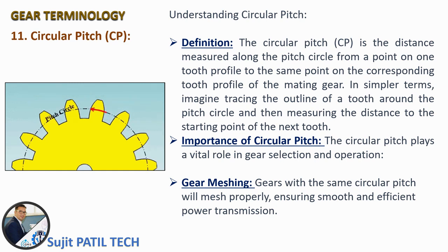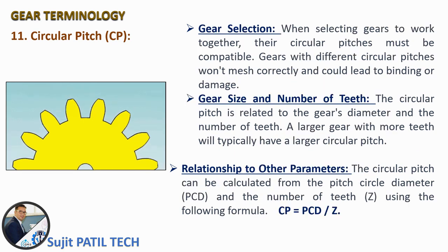Importance of circular pitch. The circular pitch plays a vital role in gear selection and operation. Gear meshing. Gears with the same circular pitch will mesh properly, ensuring smooth and efficient power transmission. Gear selection. When selecting gears to work together, their circular pitches must be compatible. Gears with different circular pitches won't mesh correctly and could lead to binding or damage.